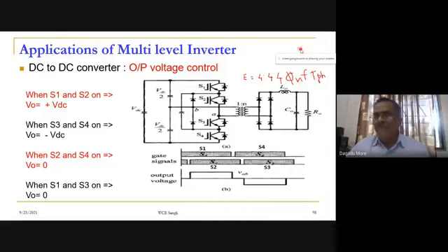And out of that, if my frequency increases, the voltage per turn, if you take T_ph here, so E by T_ph will be the voltage per turn. So if frequency is higher, voltage per turn will be more, or we require a smaller number of turns for the same flux. And when the frequency is high, it means that our transformer size will reduce. So a high frequency transformer is always compact as compared to a power frequency transformer.